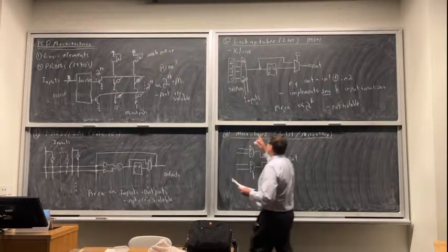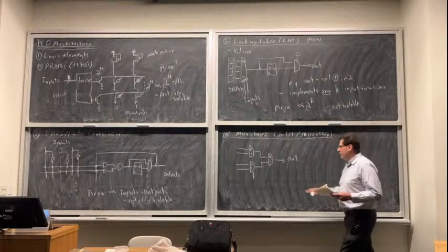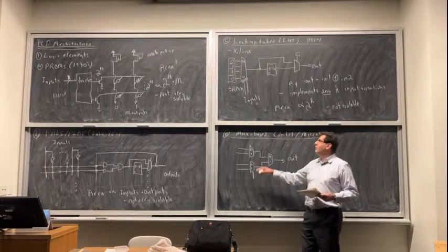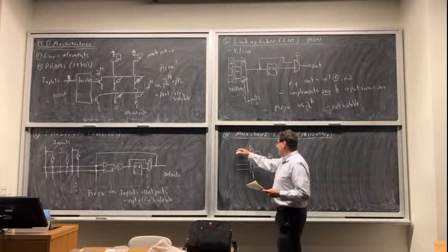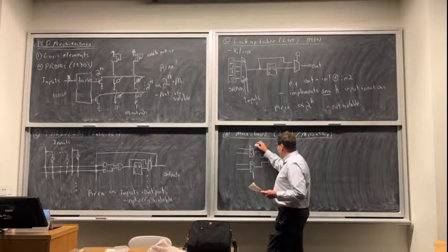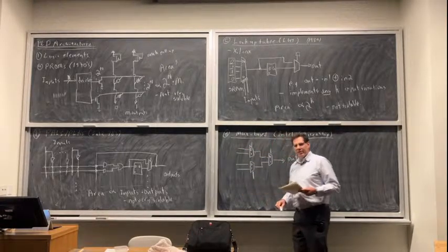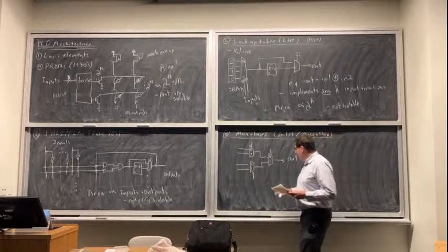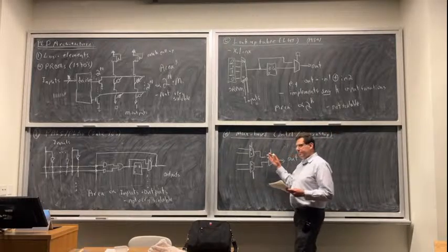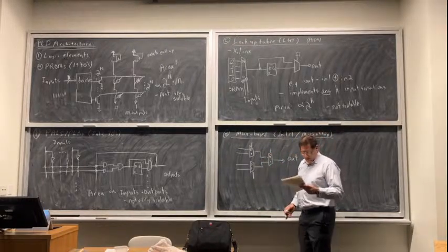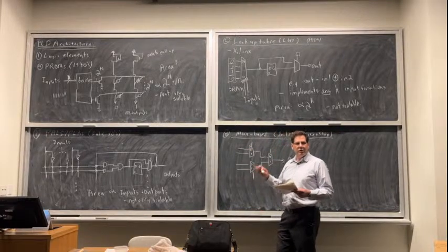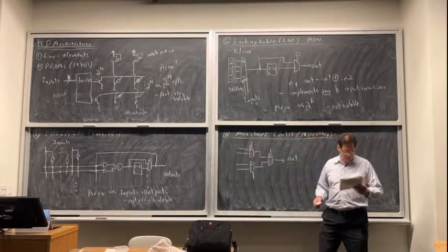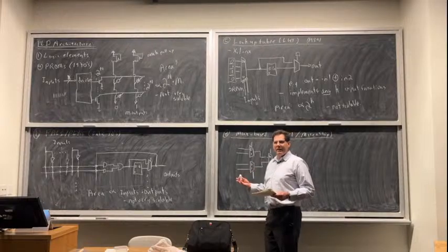It's kind of like a lookup table, because this is actually a 4-to-1 mux, which is what I've got in that lookup table there. But we do connect the select inputs of the muxes to just inputs to the logic element. Instead of connecting the data inputs of the muxes to SRAM, we just connect them to other inputs to the logic cell.